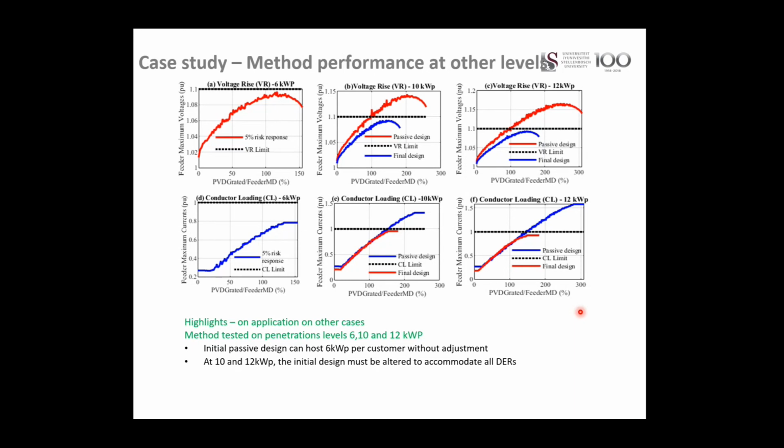But for now, since there's still a lot of reliance on our own network, I think it's a requirement. Number two, the issue of reverse power flow that might occur across your distribution transformer is also a concern as well. And I see Lewis has pegged the voltage at 110%, but maybe it's going to have to be lower, depending if your transformer is either bucking or boosting, to allow for the voltage rise across the transformer or drop, depending.